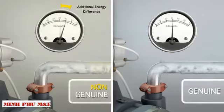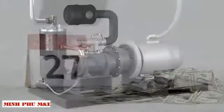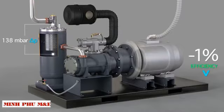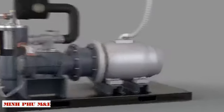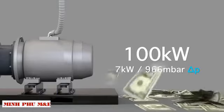Multiply this extra power requirement across the life of the filter element and costs soon start to accumulate. As a basic rule, for every 138 millibars pressure difference between the pressure vessel and the delivery port, your motor becomes 1% less efficient, adding 1% more to your running costs. So a 100 kilowatt motor would consume an additional 1 kilowatt for every 138 millibars pressure difference. The greater the pressure drop, the greater the cost.